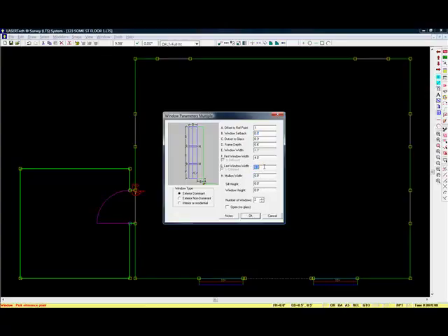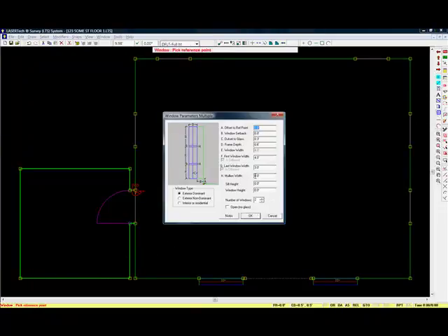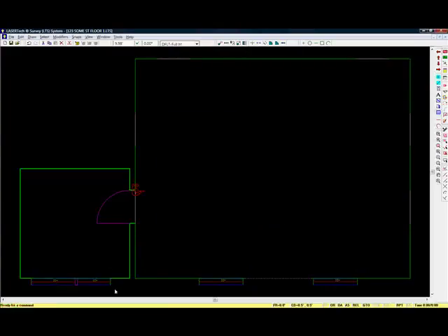Let's say the second window, we measure it and it's 3 feet. Everything else is the same, and oops, we missed one thing. We're just going to undo that. We missed the mullion width. We'll place the windows again, and there's a mullion width. So the mullion we'll say is 0.2 feet, and we place it like so.